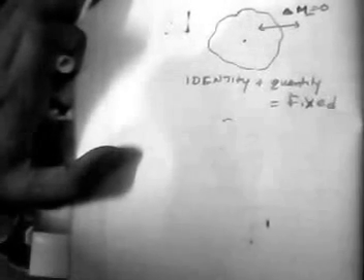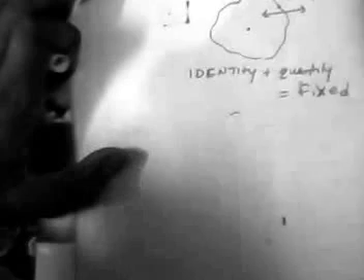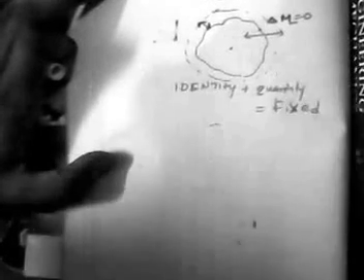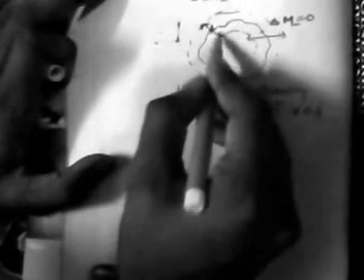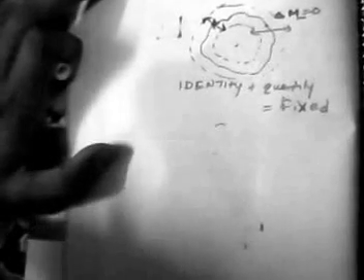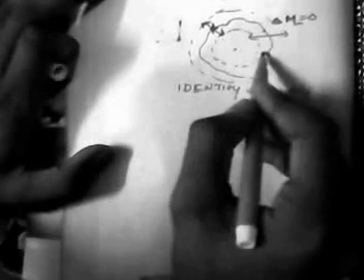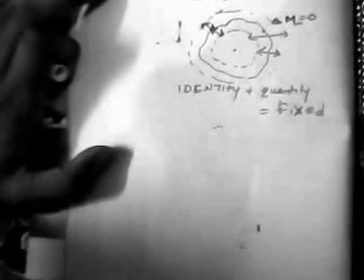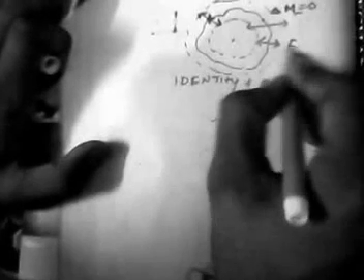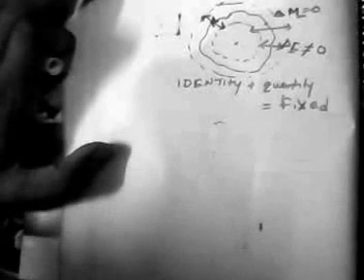Another thing to discuss is the energy interaction. If this system expands or collapses with respect to the boundary, then definitely it will do some boundary work. If it is expanding, this is the amount which increased, and if it contracts, this is the degree of contraction. So the energy interaction can occur through boundary work. That means in a control mass system, the only thing we can say is that mass interaction is 0. Energy interaction is not 0.